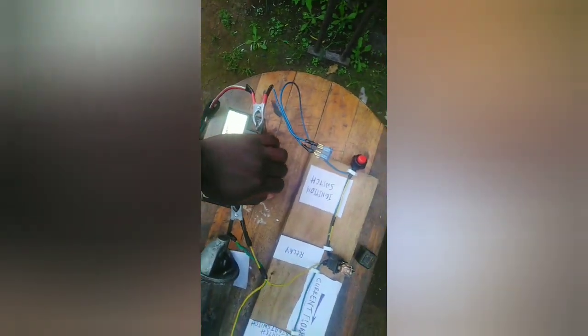So when your car is not starting, you might want to look at the voltage of the battery. Maybe your battery might be dead. Maybe you might have an open connection. An open connection is where your wire may be cut or damaged, and causes current not to flow.